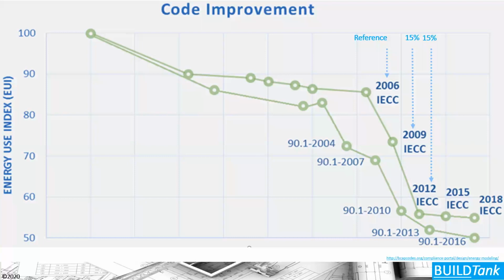So we moved from about 7 air changes per hour to 3 air changes per hour in our climate zones here along the Front Range of Colorado. Now that became a mandatory requirement to do testing, and that really got people's attention because people didn't understand how easy it would be or wouldn't be to achieve that level of house tightness, because there wasn't a significant amount of testing happening before that time period. At least that was the thought process on a national level.